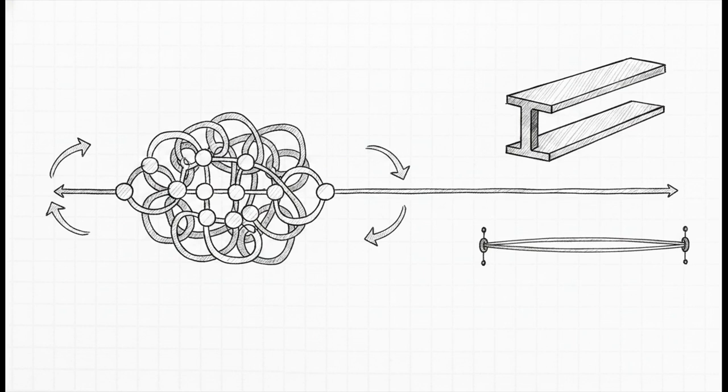Elasticity happens because those randomly coiled amorphous chains uncoil when you pull them and then snap back when you let go. Hooke's law lets us calculate exactly how stiff that material is going to be. Young's modulus, that's the E, is just stress divided by strain. High modulus means it's super stiff. Low modulus means it's flexible and rubbery.